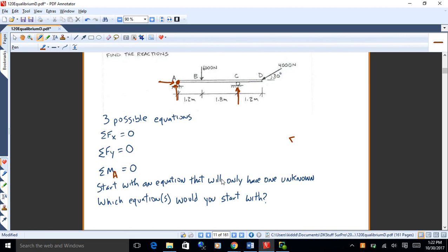We good with that? What if it were a cantilever? Cantilever, we'll get to one of those next, but really the solution process is pretty simple because you just go sum of Fx, sum of Fy, and sum of moments about the support and you're done. There's no strategy to how to solve a cantilever because all the reactions are in one spot.